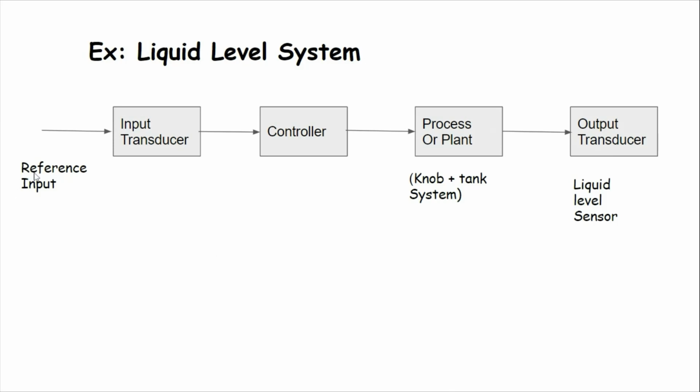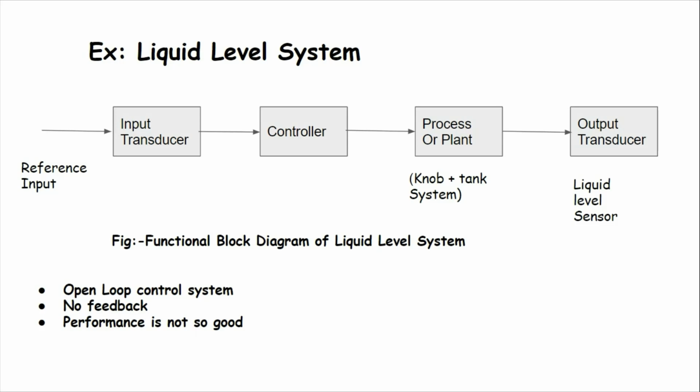Our desired level is the reference input. So here some important issues are that there is no feedback from this output transducer to this controller, the input side. The person moving the knob does not know what is the exact output, the actual output.